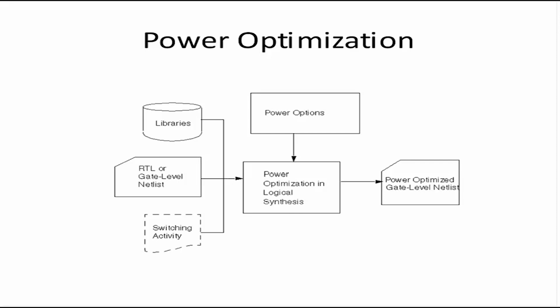It gives a lot more advantage later in the field. Later, when you want to set some special constraints or do some separate optimization, the presence of ICG will help a lot, because now you have one particular type of cell. You know that this cell is used for clock gating, and you can use some typical scripts to extract those cells and do things on them. So it always helps to use ICG. The first principle: you should always look into the library and see if the ICG is available.